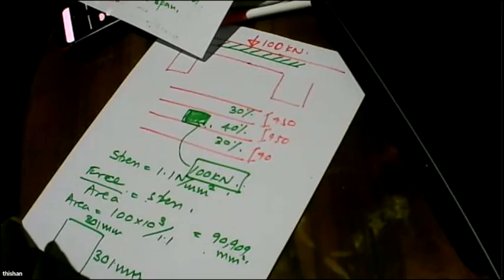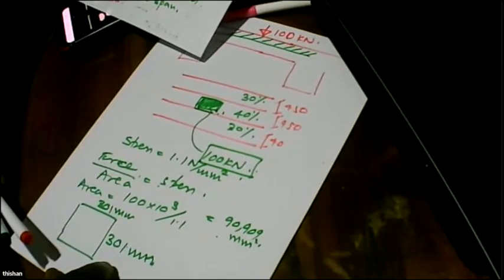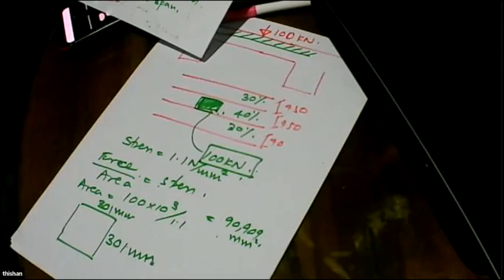There are research papers published in engineering journals covering this type of testing for precast panels. So our conclusion was, directly under the load, you can say 40% of the load is carried by the panel directly under the load, and the remaining 2 panels will carry 30% each.